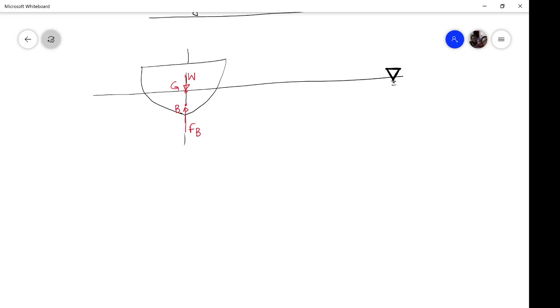Now what will happen if you disturb this body? If you disturb this body like this, if you look very closely, this was the original line of flotation. That means the line which is aligned with the free surface, at which it is floating actually. So the moment you tilt this body in this particular direction, you will see that this much volume has moved out of the fluid and this much volume has moved into the fluid.